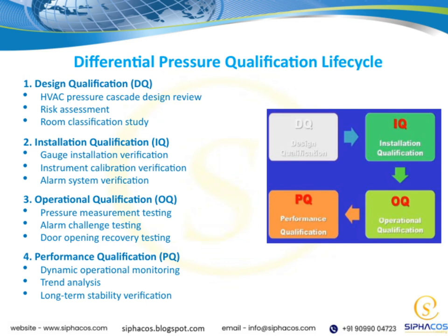Then, operational qualification puts the system to the test, measuring pressure, challenging alarms, and checking door recovery. Finally, performance qualification monitors the system in real conditions, analyzing trends and confirming long-term stability. Each phase builds on the last to ensure reliable, safe operation.